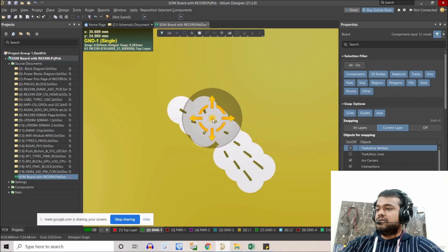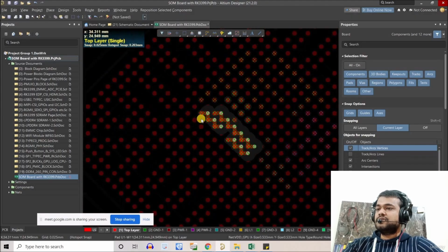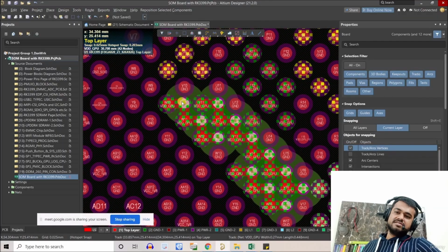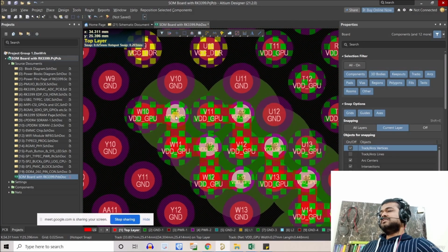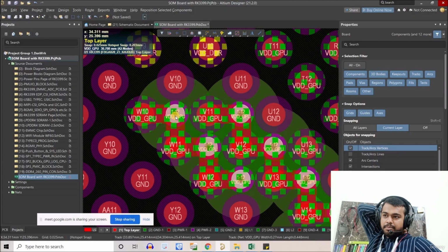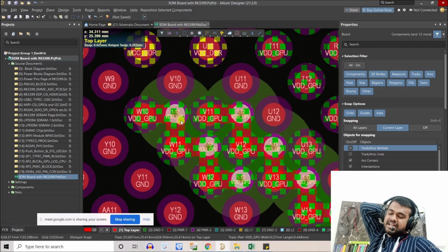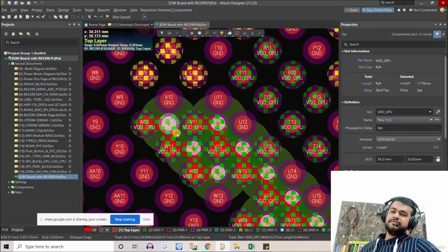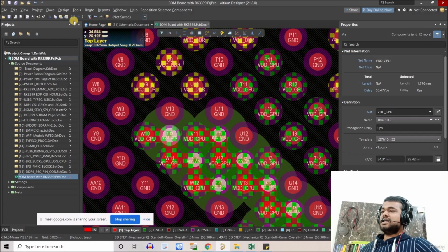So we're going to use around 8 mil or 7 mil as per our requirement. So again, how I decided what the clearance should be: you can just imagine, right? As per your past experience or whatever boards you have designed, what should be the clearance between a pad and the ground, right? It should be a minimum of 10 mil or 8 mil, something like that. Sometimes we can go for 6 mil as well if required. So there is not any kind of hard and fast rule. You have to follow that clearance only. This is just a power net and a ground, right? So you have to think like that.